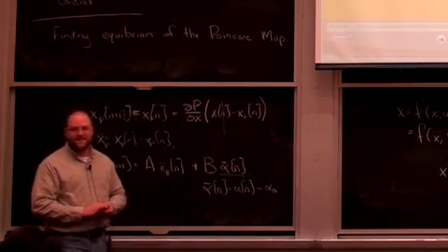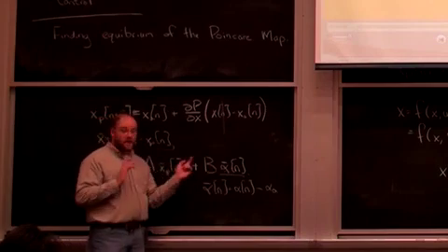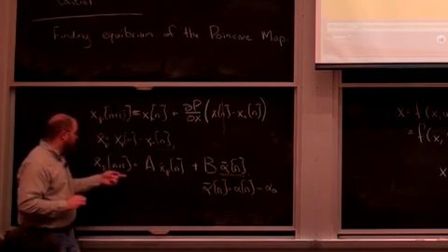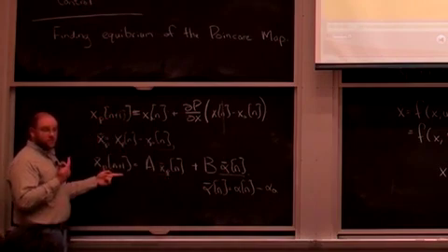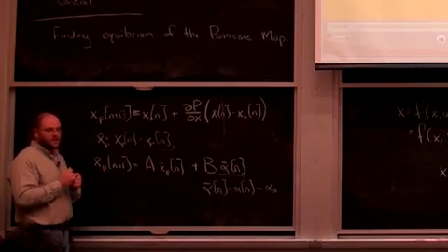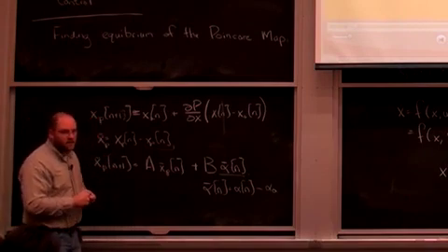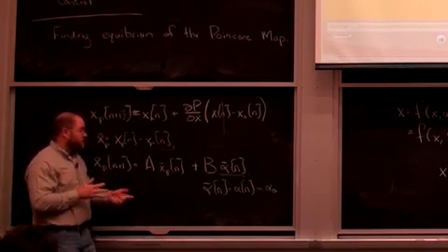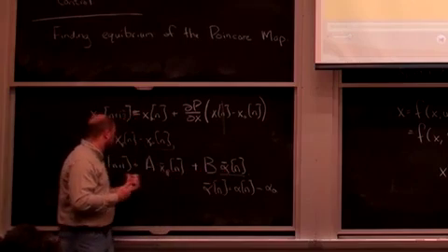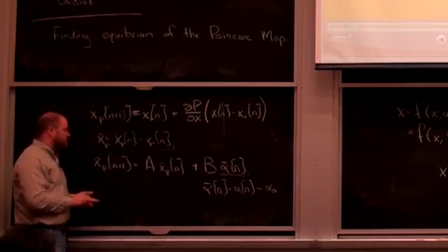Yeah, good, right? So in discrete time, I can actually find an action, potentially, it depends on B, right? I could find an action which would actually drive me to 0 in my error dynamics in a single step. In continuous time, getting there arbitrarily fast means setting your gains arbitrarily high. In discrete time, that's not the case. I can set a finite magnitude gain that will get me to 0 in a single step. So that's called deadbeat control.